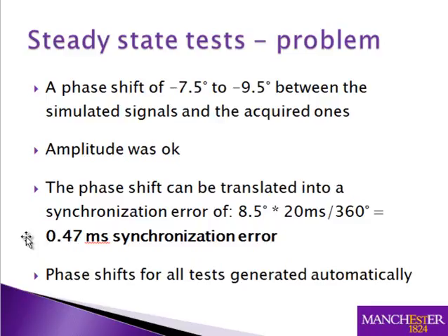At the transition at the pulse of the GPS, so we should have started the cosinusoid at exactly the time when the PMU reference was at 0. So the PMU should have measured 0, but instead it measured like -8, -7.5, -9 point something.